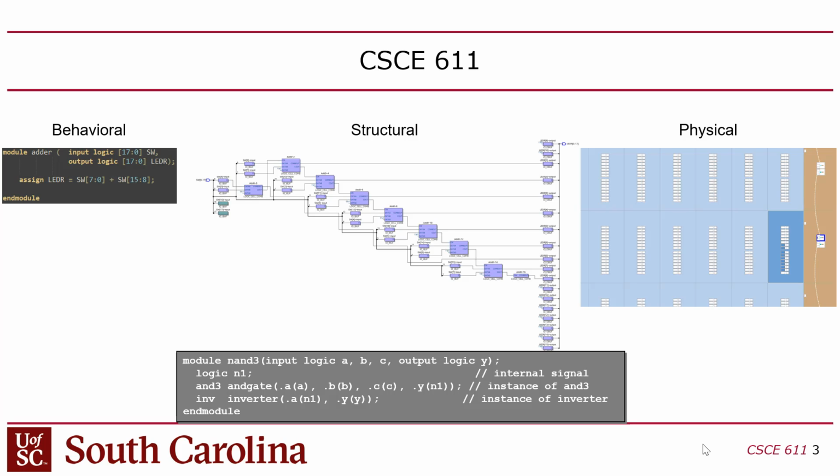We're going to be defining the behavioral description using hardware description language, or HDL. It's a little bit more abstract than just writing Boolean logic. However, HDL can be lowered down into Boolean logic, right? You can take your HDL code and convert it to Boolean logic, but the HDL code being more abstract makes you more productive because you can write things in a more abstract way, and the HDL code may generate a lot of Boolean logic that you don't necessarily have to write.